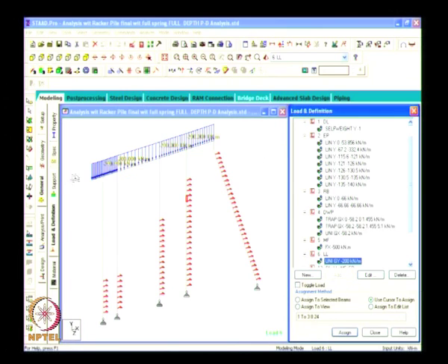So this is the live load on this, which is about 50 kilonewton per meter square, but we are applying 200 kilonewton per meter. It is mainly because we are taking a 4 meter width. So whatever load is coming on the slab, which is 4 meter this side, it will go into this. You have to see the axis here, x axis is along this line, y axis is vertical, and z axis is perpendicular to the plane of this paper or laptop. So it will be perpendicular to this.